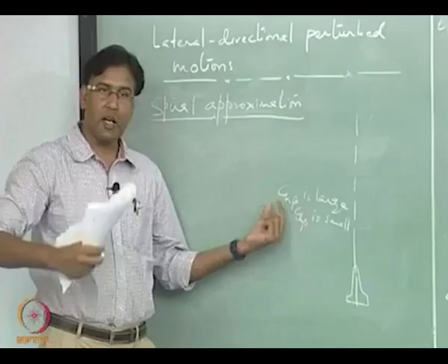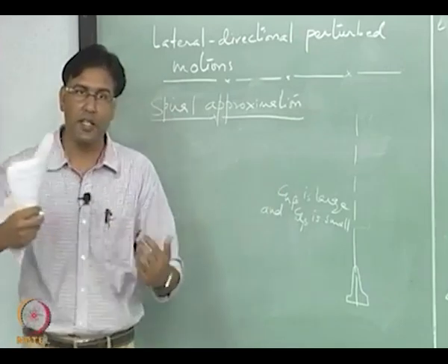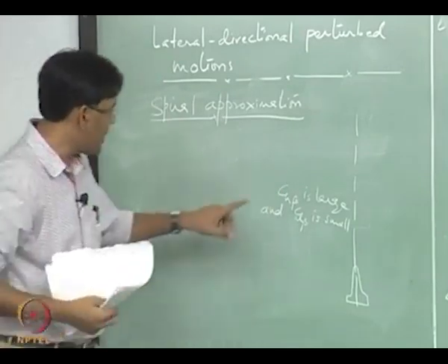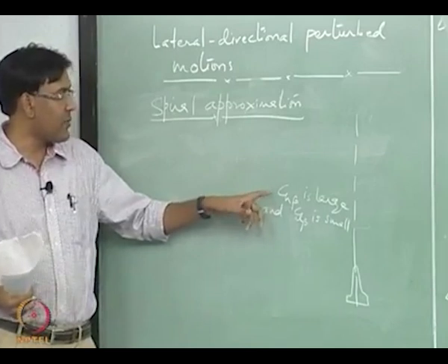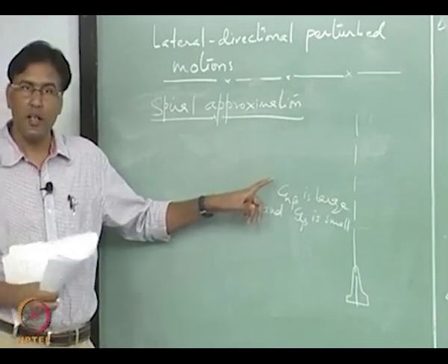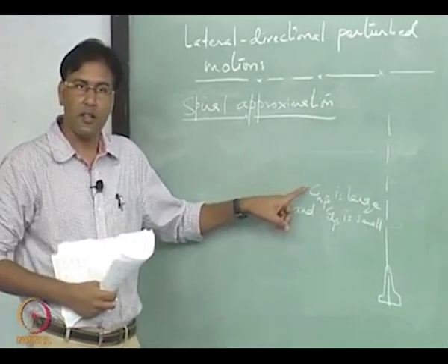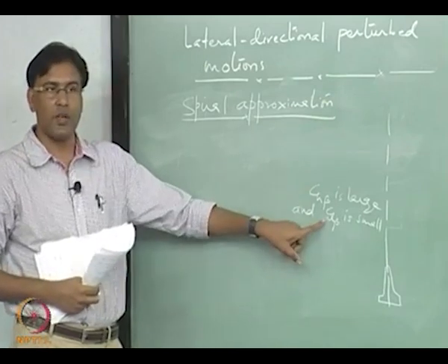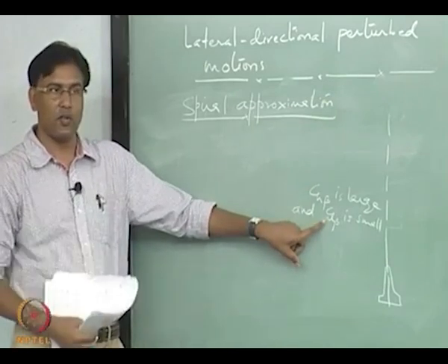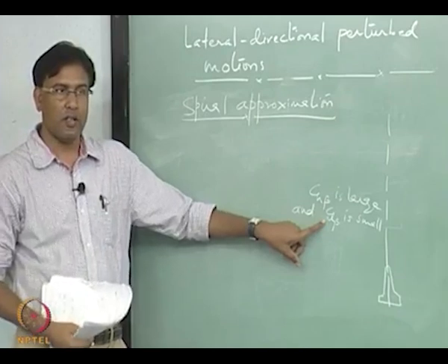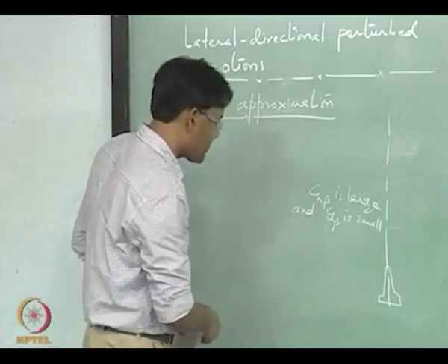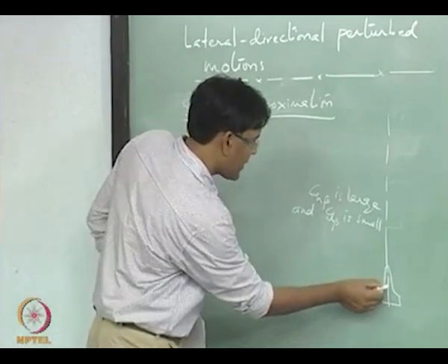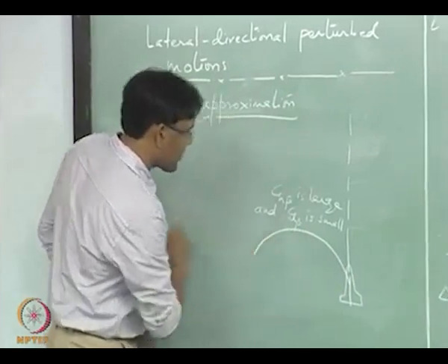in delta beta, because of the side slip perturbation, and that side slip is constantly being killed because of this large stiffness in yaw, right, but it is giving you a roll because this Cl beta is low, right. So, the aircraft is following a curved path which is something like this.